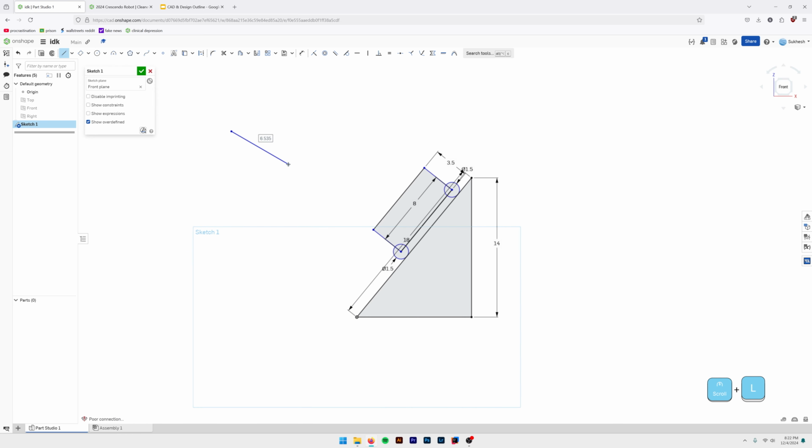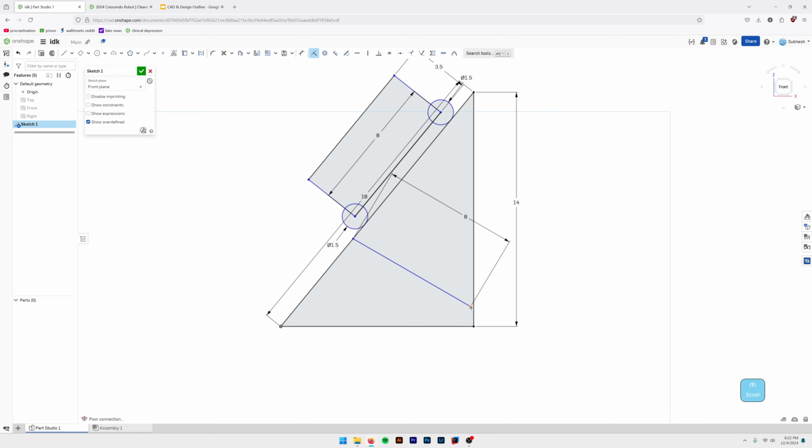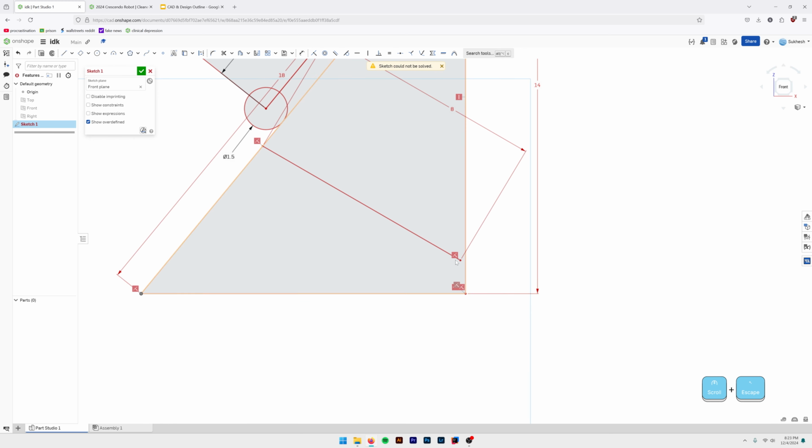Similarly, a lot of errors that you might come into, if I dimension this and then try doing sketch constraints, so like I with here, it'll work like that, but let's say I wanted to try to coincident with this. It won't work because this point cannot touch this point because I've limited to 8 inches.